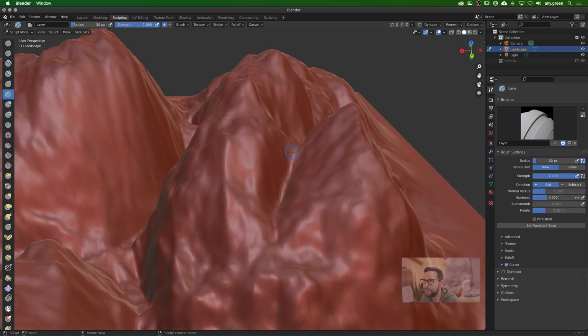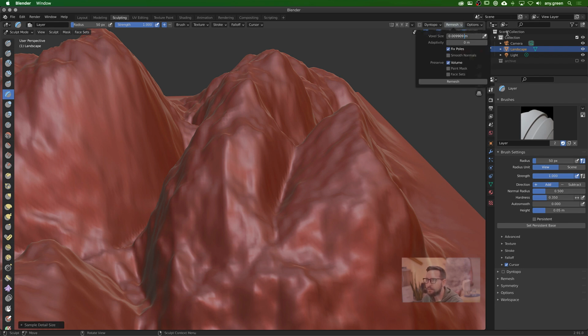Of course, it's a little bit irritated because we don't really have enough details here. So let's try to use a remesh, and let's see what our resolution is. Well, it's already pretty fine, so let's get this even finer. So let's maybe go to 3 and do a remesh. By the way, do not try to create kilometers worth of mountains if they don't have to be together.